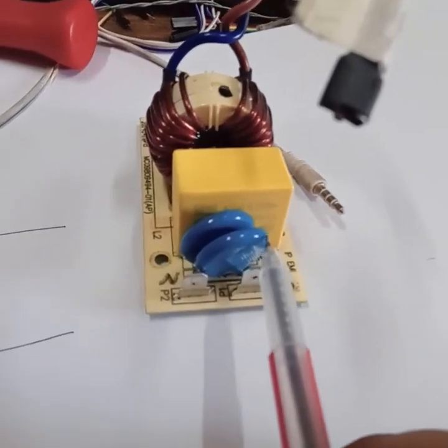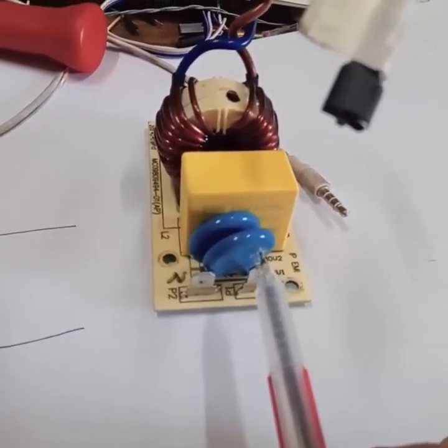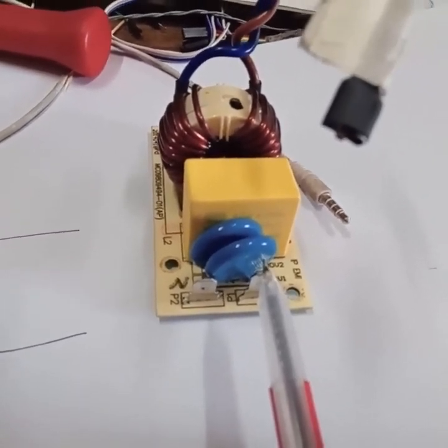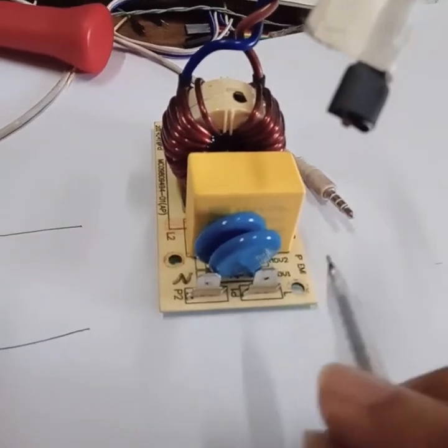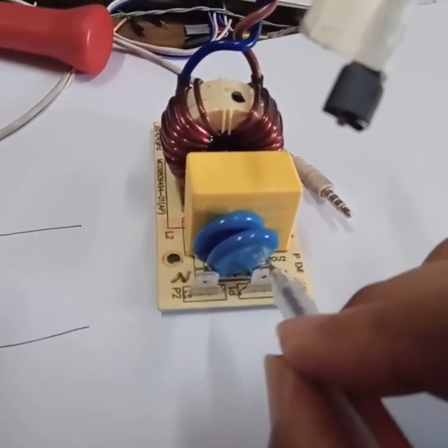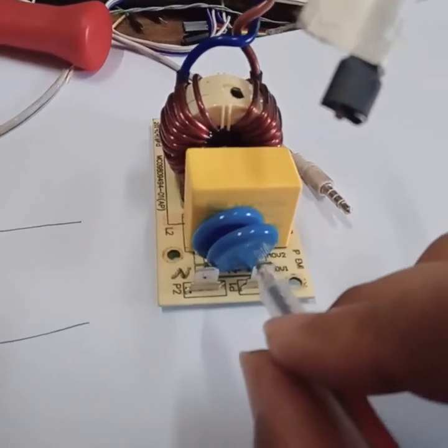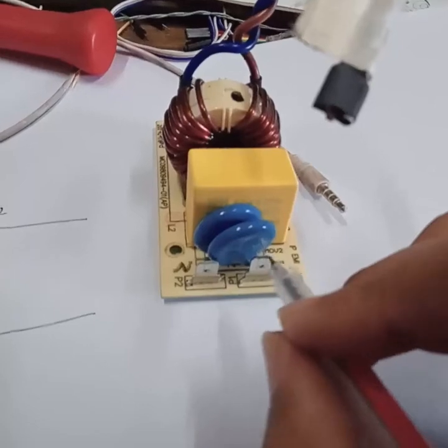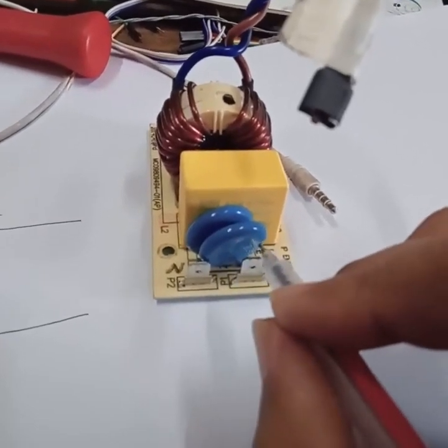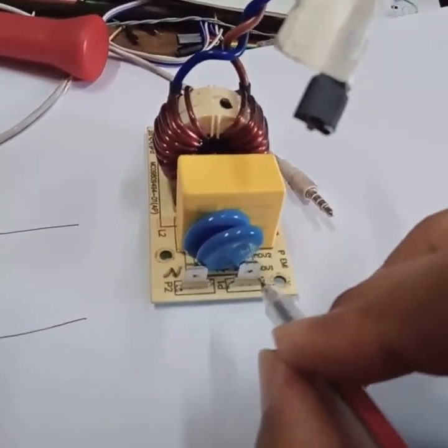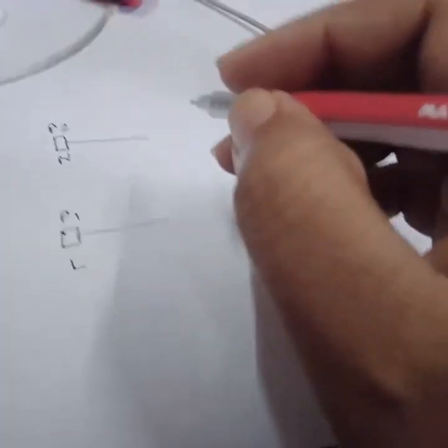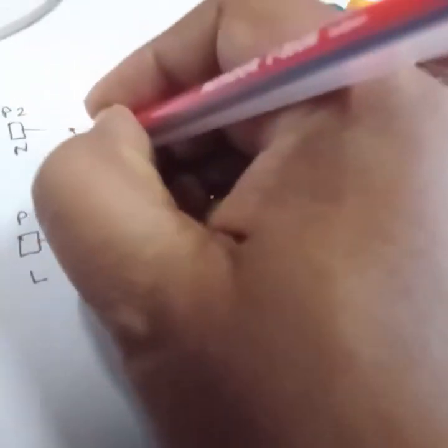varistors. Actually, a varistor is used to remove the spike in input voltage. A 400 volt spike may enter your single phase line system. Normally single phase line voltage is 230 volt, but a spike of 400 or above may come into your system. At that time this varistor becomes short and bypasses that spike. Here are two varistors. The symbol for a varistor is like this.